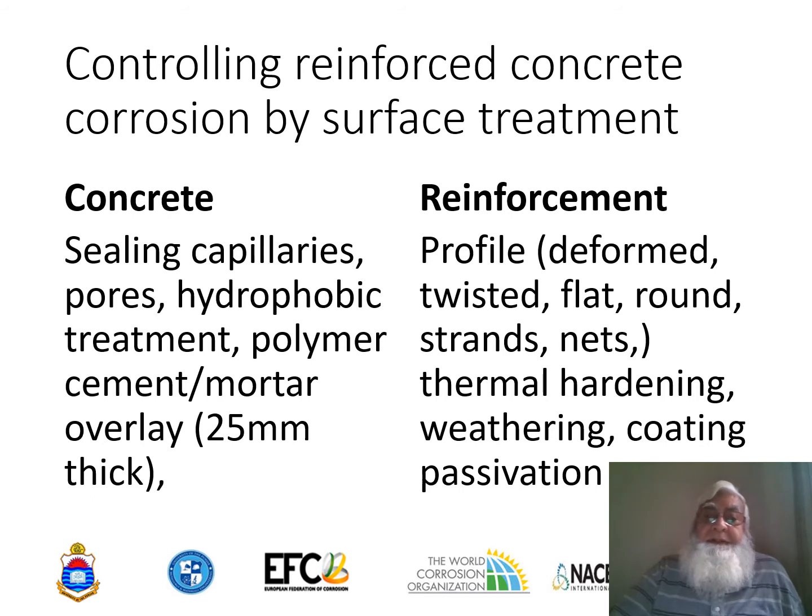That's a thermal hardening, right? So the steel is a thermal hardened weathering steel, which develops a very thin rust layer which can behave as a cathode and can lower the rate of corrosion of the steel. And then we can always apply inorganic coatings like phosphates, chromates, and other coatings, and passivation is done either to the steel or to the stainless steel or